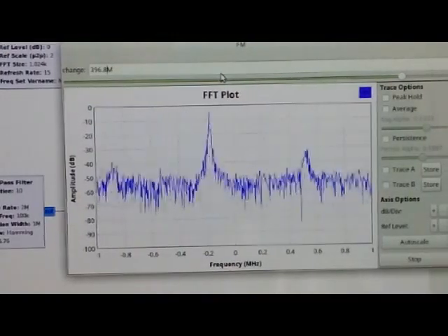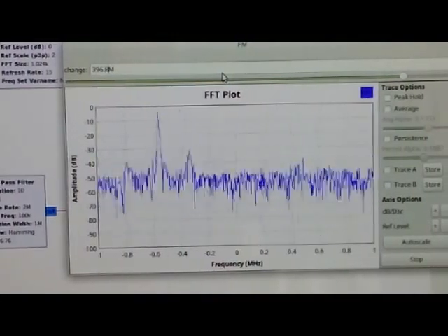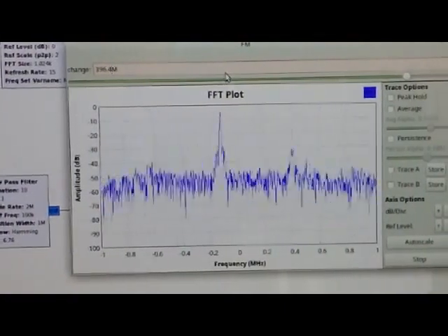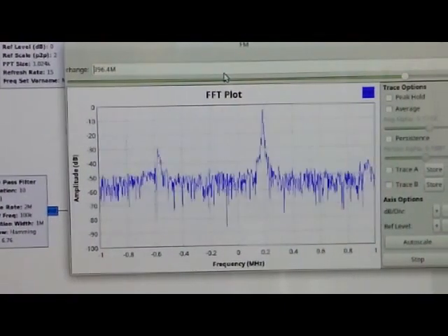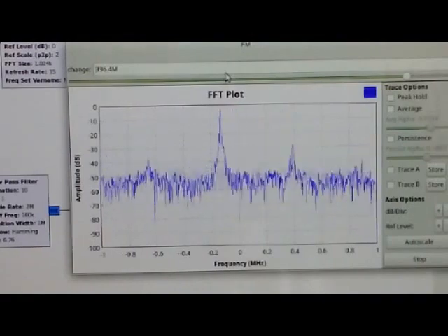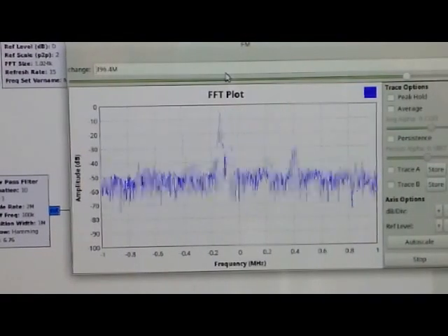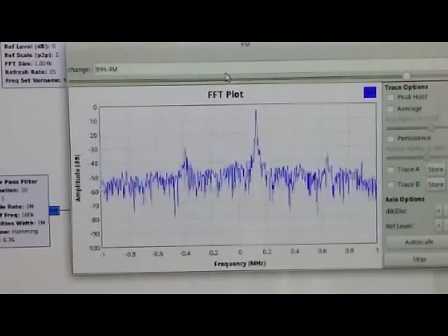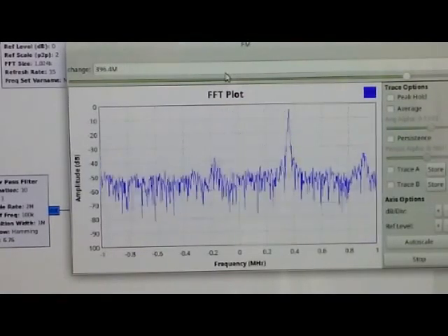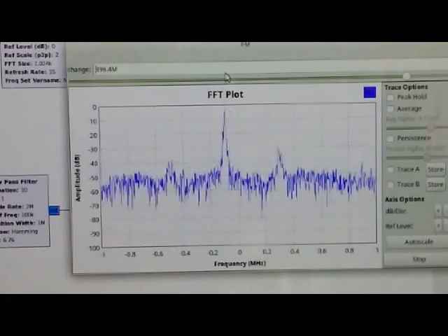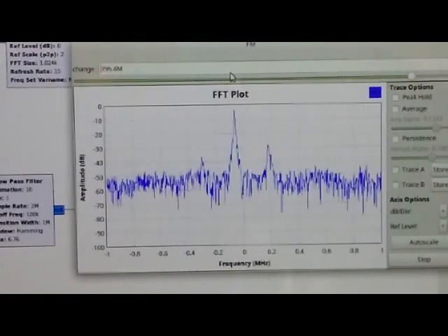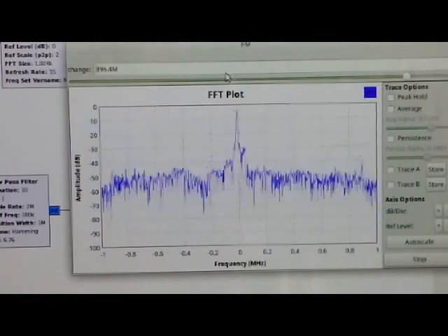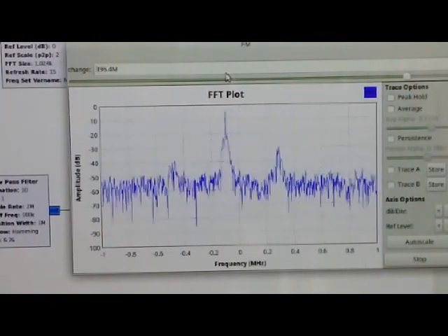Can kind of just adjust this parameter here. And subtracting about 0.4 of a megahertz should bring us right in the center. Nice. So yeah, if we're picking that up at 317, we should just be under 400 megahertz, and we are, 396.4. And I've found these elsewhere, also around 240, 160, and 80 as well.